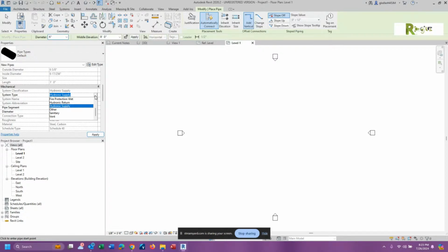So what I'm trying to do is sort of set you up. Now I want you to go draw a piece of pipe. You're good with hydronic supply. Go click on the screen and draw. All right, not bad. Now, do you remember where I said was the speedometer area of your Revit file? It says right now that you're drawing a 6-inch diameter pipe at 9 foot high, right? And we know what type of pipe, the default type, and it's a hydronic supply. So go ahead and put a click.